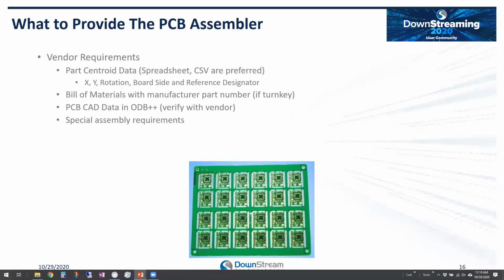A lot of our contract manufacturer customers, sometimes they'll just get Gerbers and a component list. We highly encourage trying to use one of the more intelligent formats when delivering that information. And you can limit the intelligence so that you're not giving away things. But most of the intelligent formats, and particularly IPC 2581, allow you to dumb down the data on output so that you're not, as they say, giving away the farm as you give this off.